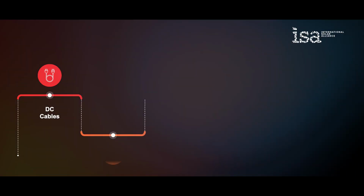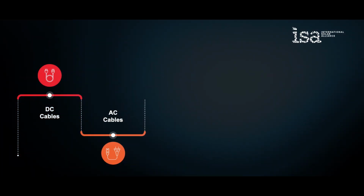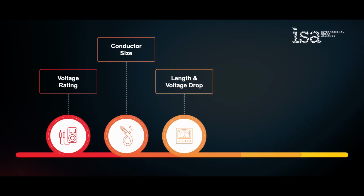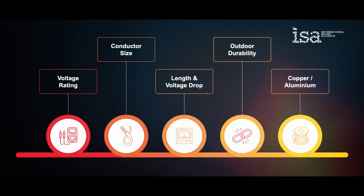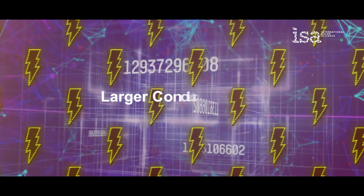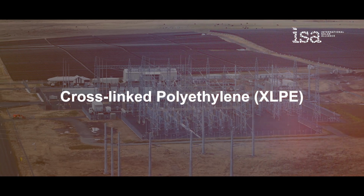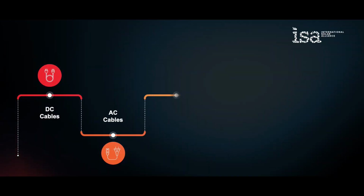AC cables carry alternating current from the inverter to the grid or loads. Selection depends on voltage and current ratings, single-phase or three-phase output, length of run to manage voltage drop, environmental exposure, conductor type, copper or aluminium. Longer cable runs require larger conductor size to minimize losses and maintain system efficiency. AC cables may have XLPE, PVC, or LSZH insulation depending on the application.